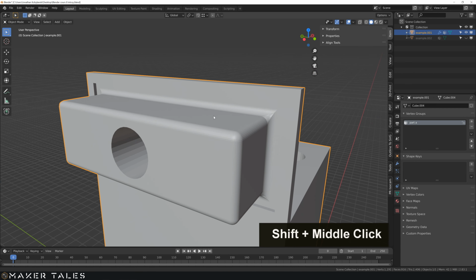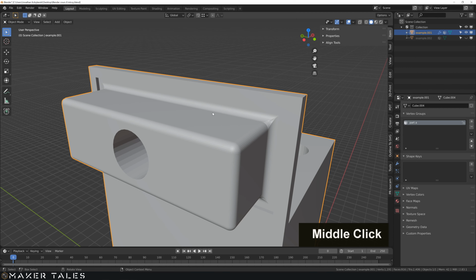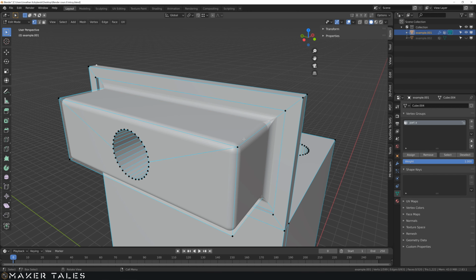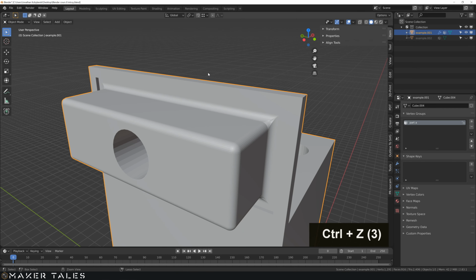The main word here that's being used is vertex group. As we know, a vertex is all these little black dots when we're in vertex select. So an edge is a collection of two vertices. Now, because this vertex is selected and that vertex is selected, it has filleted this entire edge as well. So the only way to go about fixing this issue is let's go ahead and undo what we've currently done by adding that into the vertex group.